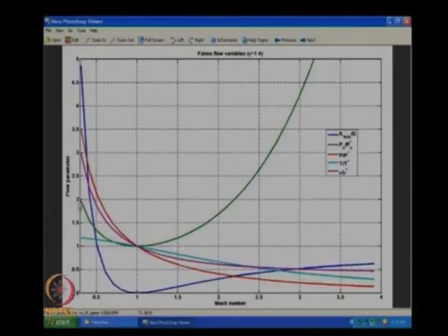Okay. If I think about 5 meters at, say, 0.2, 0.3 Mach number, from there it is going to 4 meters, 3 meters, 2 meters and 1 meter. It travelled 4 meters for that particular f by D, till it became 0.5 Mach number. I started at 0.3 and it ended at 0.5 while the tube was 4 meters long. If I go 1 more meter, it of course is going to reach Mach 1. When I go closer and closer to Mach 1, this particular flow is very sensitive to the friction. Till that time it is not. Subsonic flow is not at all sensitive to it.